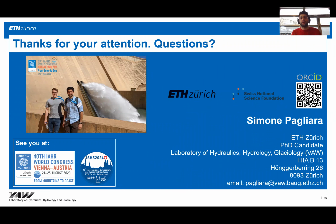Yeah, very good question. Thanks, Emanuele. Yes, potentially. There is a lot of energy in these fast flows. We reach velocities up to 60 meters per second in prototypes. So ideally, yes. There are only two criticalities that come to my mind. The first is that low-level outlets are safety structures, so we don't want to occlude them in any way.